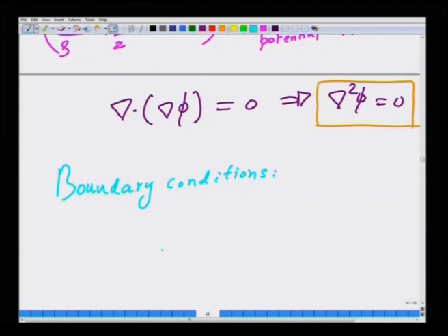Okay. When we went from the Navier-Stokes equation to Euler equation, we dropped the viscous term. The viscous stress term had del squared v, that is second order derivative in space. When we neglected that term, because it is multiplied by 1 over Re in a non-dimensional sense, we have lost the highest order derivative term in the governing equation when we went from the Navier-Stokes to Euler equation. The Euler equation had simply v dot del v term, and del v has only first order gradients in spatial locations.